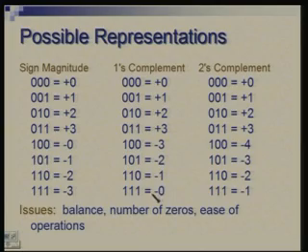Okay. Now, what is the definition of this representation? This is basically, for negative numbers, in magnitude 1 more than 1's complement. Okay, 1's complement is defined as flipping all the bits, and let us say if you take a number like -2, okay, so its 1's complement is 101 obtained by inverting all the bits, and if you add 1 to that, you get 110, you get -2. So, 1's complement plus 1.